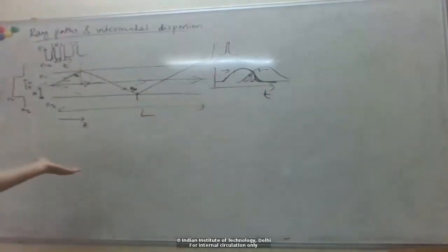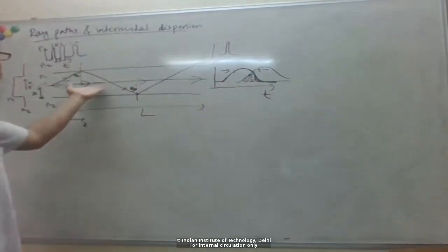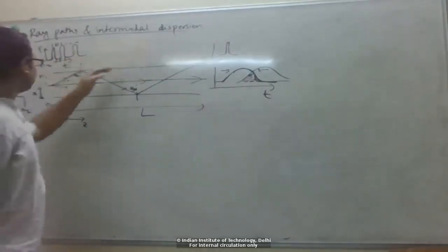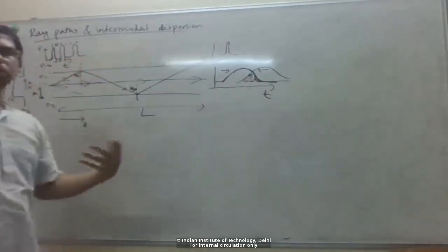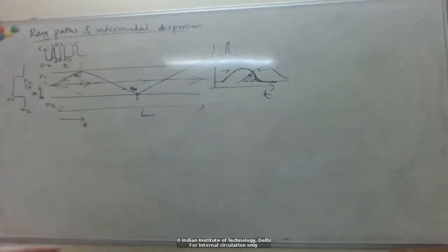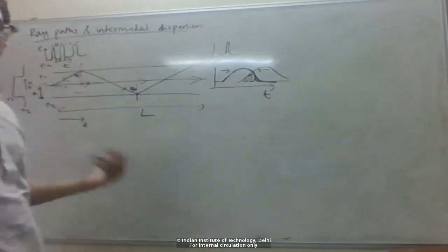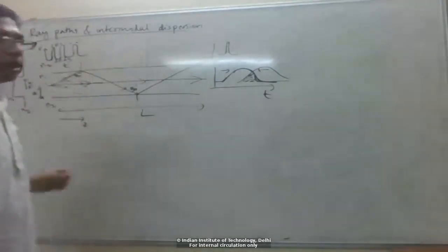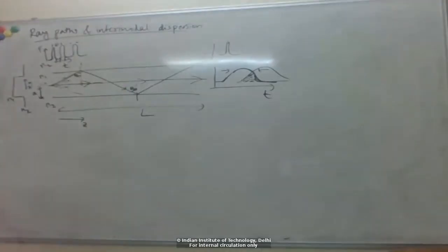That's why you want to minimize that dispersion, so that you can operate at high bit rates and low errors. This particular phenomenon is called intermodal dispersion because, as I said, these different rays are like different modes, and the differences between the modes cause it. There are other types of dispersion that we'll discuss later in the course, but this is the biggest one, so that's why we're discussing it first.